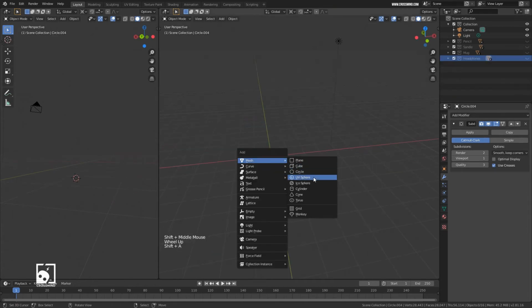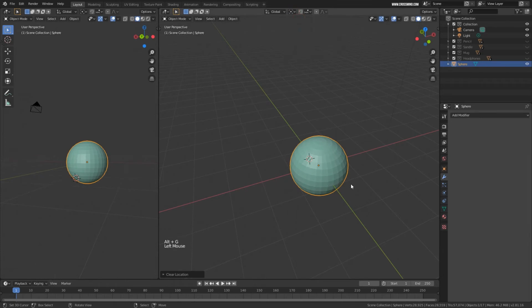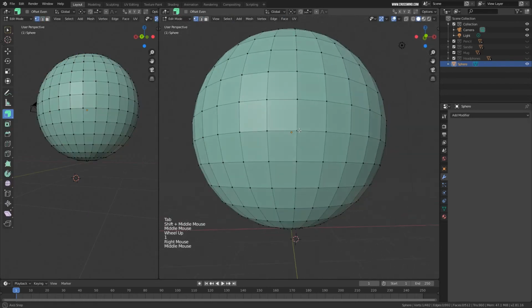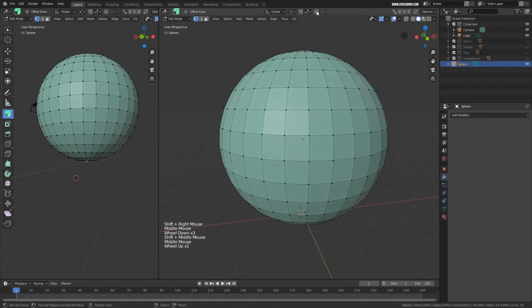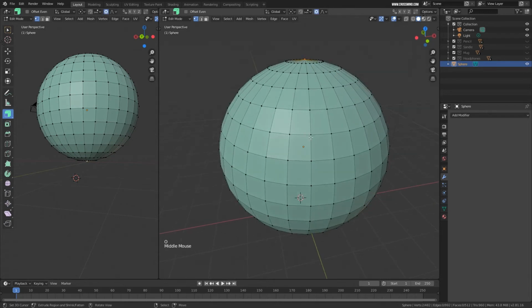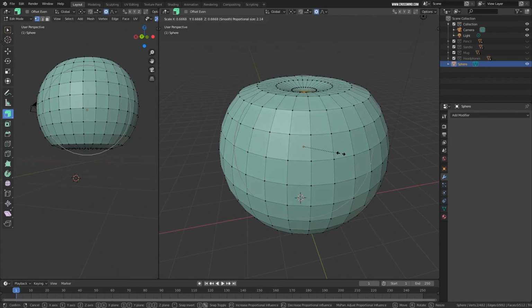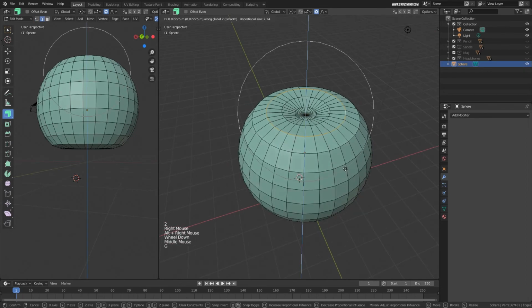Now we'll create one simple apple. To do that, I'll bring one UV sphere over here and scale this up, okay, from bounding box center. All right, now what I can do is I can start shaping this sphere we have. So I can select these 2 vertices and switch this button for proportional editing, or just simply press O on the keyboard, and then I'll scale these down, and I can scale up the brush, and you can see it's pulling both the vertices towards each other, and now I can start shaping this up like an apple.